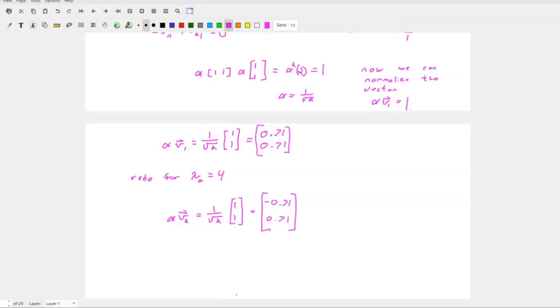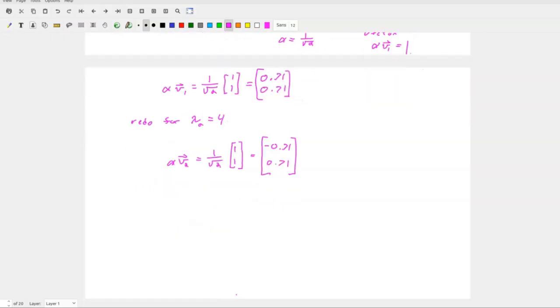Okay. Lastly, the normalized eigenvectors can now be converted to mode shapes, right? Because if we didn't have a normalized vector, we would have to adjust our mode shape to match, and that gets quite hard. So we have to normalize our vectors, and that can be converted to a mode shape. U, that's a bold U, right?